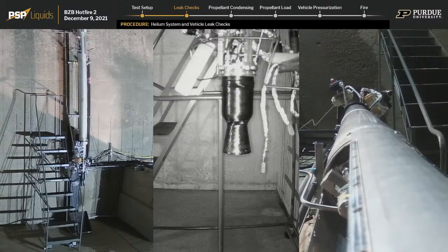The reason we don't feel it's necessary to purge the methane condenser is that it's constantly hooked up to a LOX clean system, and in that system we tape or cap off every single entrance and exit, so we have a reasonable expectation that no organic matter is moving in or out. The ideal is that everything is capped or connected to another part of the system. Tape is only a temporary measure, and we aren't using just any tape. Blue tape is a low residue form of tape, so when you tape up an entrance, you do not leave any sticky residue behind.